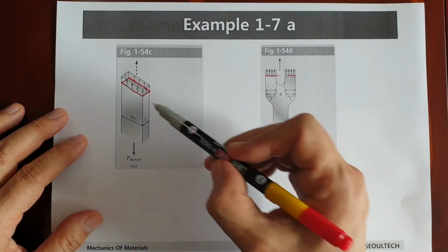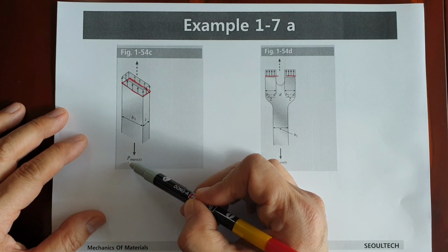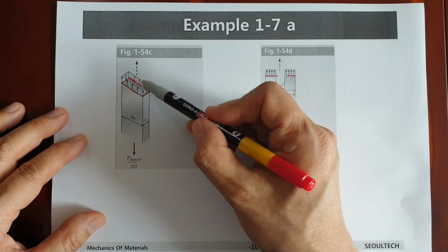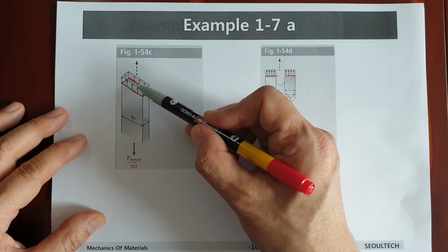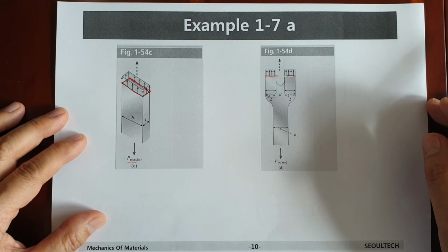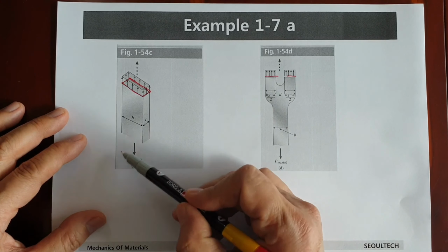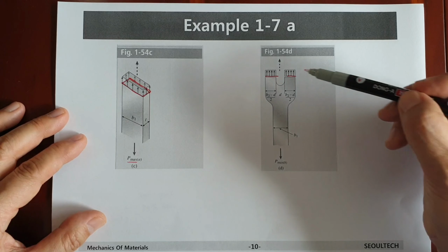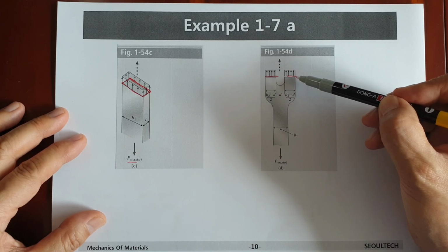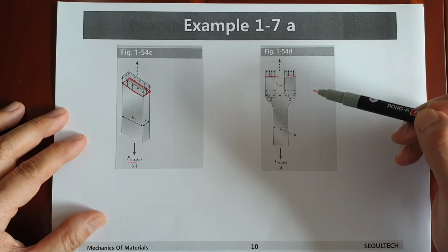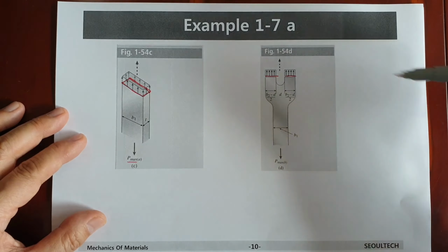When you cut there, then this kind of consideration is available. When external force is given, then it can be divided like this. Then if it is calculated and compared to the maximum allowable stress, we can find the maximum force. And near the bolt position, at this point, we have a different level of maximum allowable stress. That's why we consider this cross section.